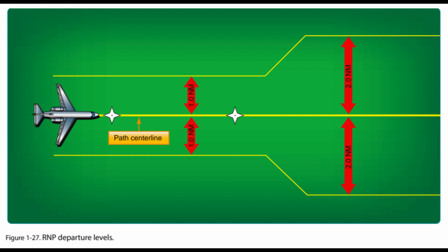These procedures generally start with an initial RNAV or heading leg near the departure end of the runway. In addition, these procedures require system performance currently met by GPS, DME/Inertial Reference Unit (IRU) RNAV systems that satisfy the criteria discussed in AC 90-100, U.S. Terminal and En Route Area Navigation (RNAV) Operations. RNAV departures are identifiable by the inclusion of the term RNAV in the title of the departure.